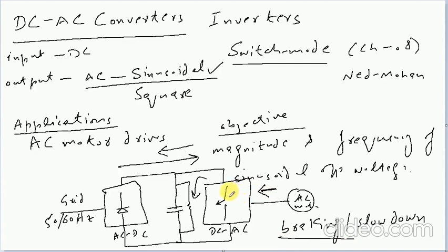Then a better alternative that could come to mind is that we either store this energy over here for that brief period, or, if this keeps happening frequently, we make an arrangement for the reverse power flow so that the power could be provided to the utility grid.